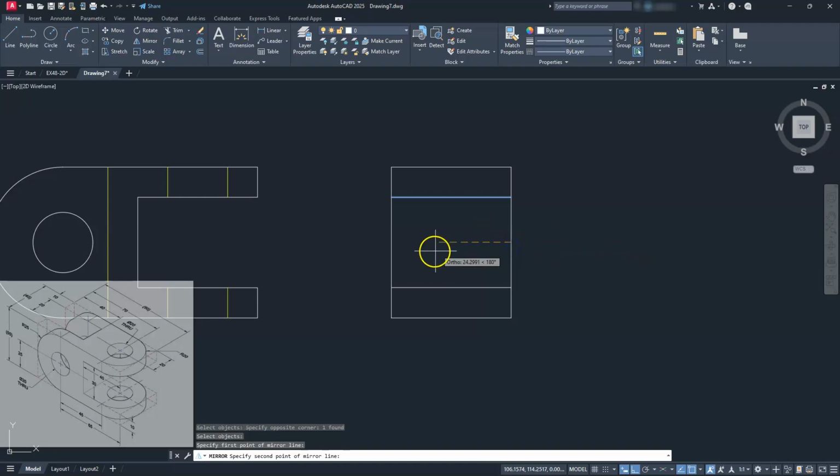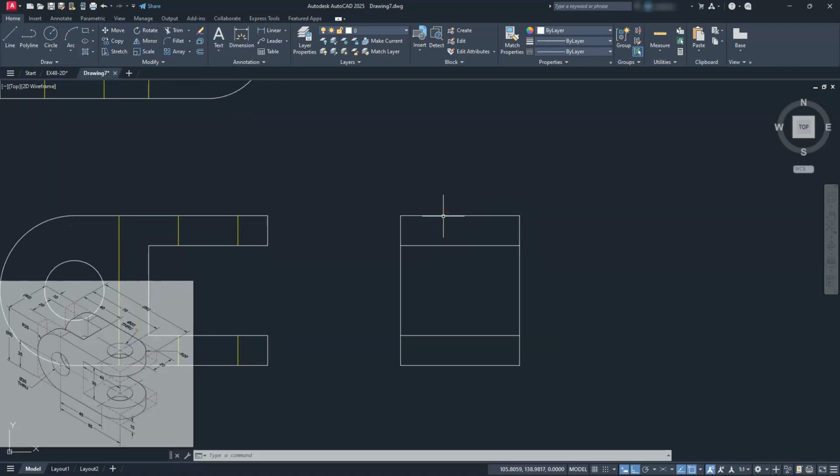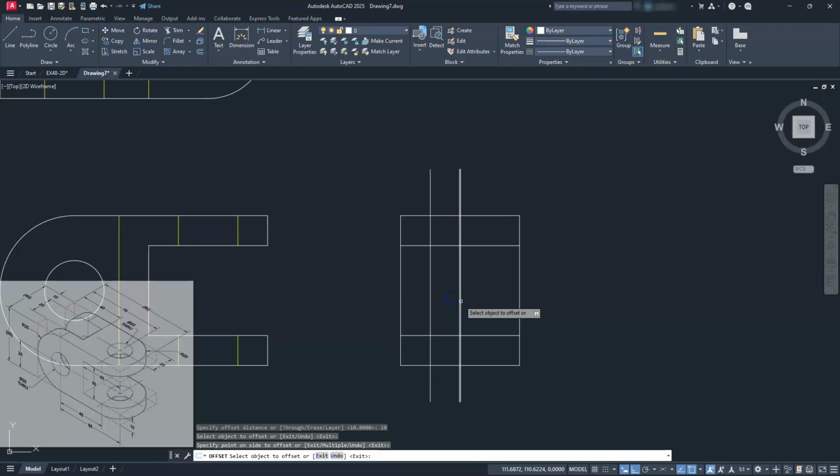While I'm telling you that, we know kind of what's happening here in the middle. We also know that there are some hidden surfaces running right down here in the back, and we do have some holes running down the middle of it, right? So we know that this is the 40 going across, and if you refer to the beginning of the video, the distance between that is actually 20. So I'm just going to draw a line, and I'm going to intentionally make this one a little longer. I'm just going to start up here and come straight down. I'm going to use the offset command, type in the number 10, and send that going across here and across here.